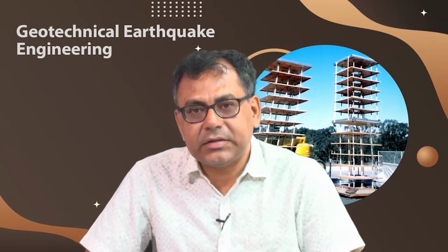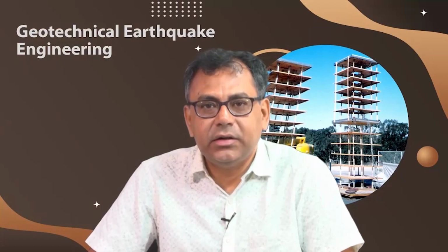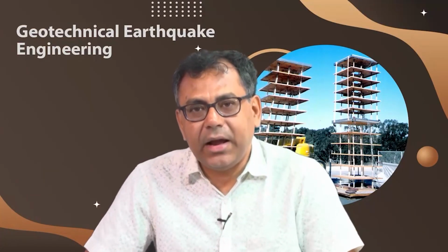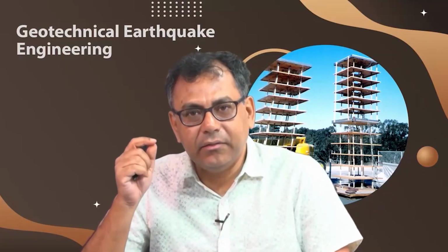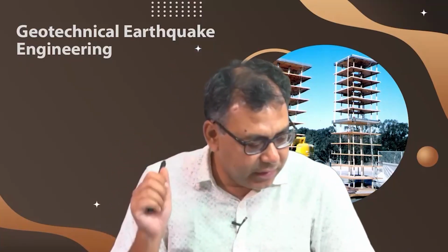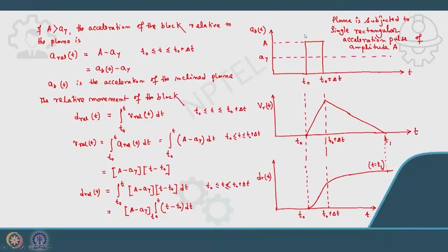So, in my previous lecture, I discussed that if a single rectangular acceleration pulse of amplitude A is applied, and if A is greater than the yield acceleration, then how the velocity and the relative displacement will change. I showed that if the pulse is applied for a duration of del t, a single pulse where the starting time is t0 and the end is t0 plus del t, then the velocity will start increasing from t0 and reach its highest value at t0 plus del t. Then it will start reducing again when the pulse is over, and reach a 0 value at t equal to t1.